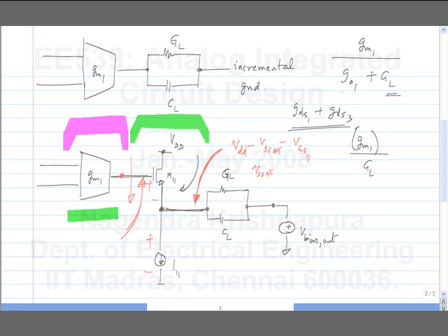So in a low voltage technology, this is not a great thing. What are typical values? Let's say VD sat is 0.15 for everything. VT is 0.6 or so. So this is some 0.9 volts or 1 volt or something, and the lower limit is 0.15 volts. So we have lost more than half of the 0 to 1.8 volt supply. That's why this is not favorable. You could have used this when you had high voltages, but now this is not a good thing to build.